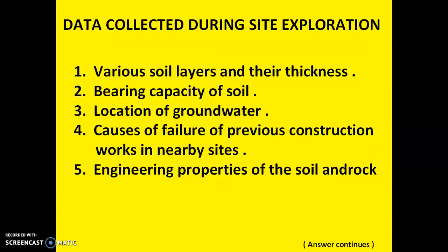The data that need to be collected during site explorations are various soil layers and their thicknesses, bearing capacity of the soil, location of groundwater, causes of failure of a previous construction work in a nearby site, and very important, the engineering properties of the soil and rock.